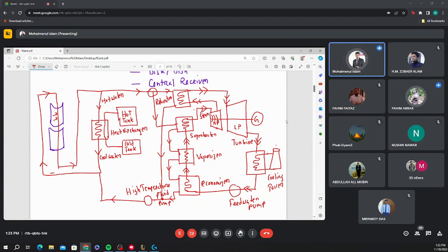There is a junction here. So you have some pipes and tubes or valves here. You are connecting some pipes with the reheater, connecting some pipes with the superheater. Also, you are connecting it to the vaporizer and the economizer. So after rejecting heat in the reheater, that water should be less heated, right?